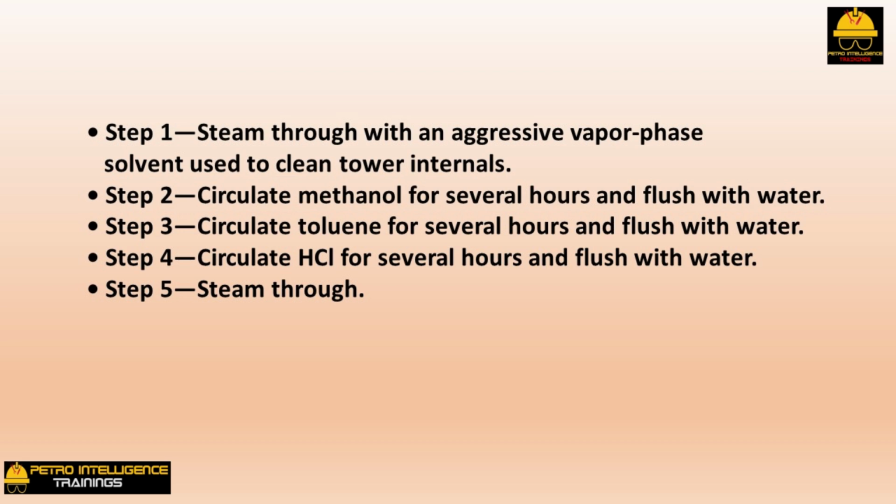Step 5. Steam through. Afterward, delta P had dropped from 25 to 20 mm of mercury. Calculated clean delta P was 5 mm of mercury. Cost of the cleaning was $130,000. The client was not pleased with this result.